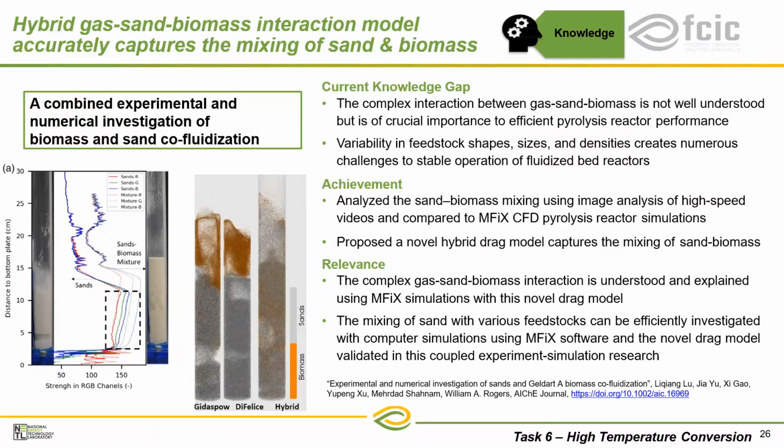If my fluidized bed reactor loses its fluidization and crashes, it takes the entire process down until we can refluidize that bed. So this work used some advanced image analysis work to capture the physical and mechanical behavior of the sand and the biomass phases. The researchers then took a hybrid drag model, which captures the key mixing effects, to create a better model that can be used to make better predictions and to understand and prevent these instabilities.